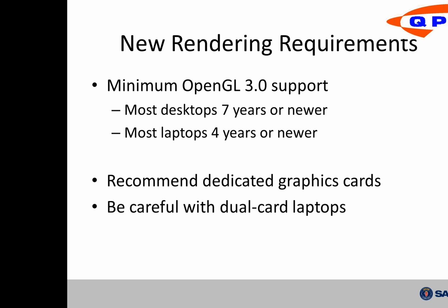So there are some new requirements to make use of this rendering. In particular, you need a video card that has OpenGL 3.0 support or newer. Now that's actually not that difficult. For most desktops, that means that it would be anything that's 7 years or newer, and most laptops probably around 4 years, because the video cards in laptops usually lag a little bit. So it's something to check on to make sure that you have a video card that does support Fledermaus with the new rendering. Now, we do still recommend dedicated graphics cards.